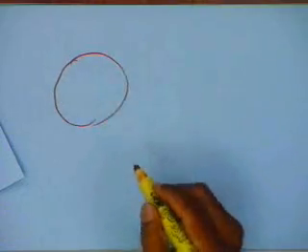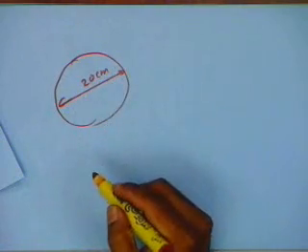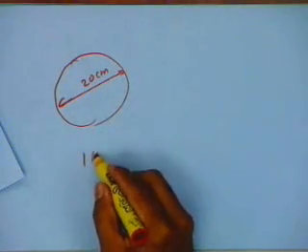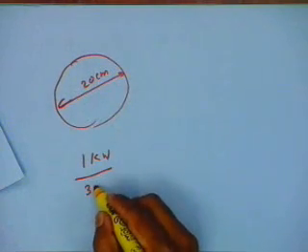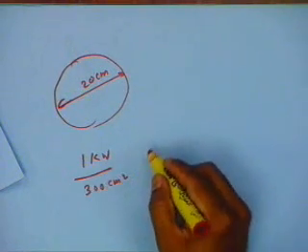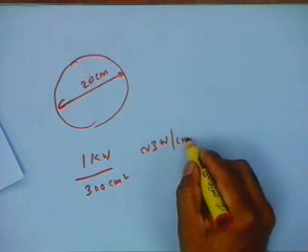Just to give an example, compare a heater which has a 20 centimeter diameter and consumes 1 kilowatt of power: with an area of pi r squared, around 300 square centimeters, this is slightly more than 3 watts per square centimeter.